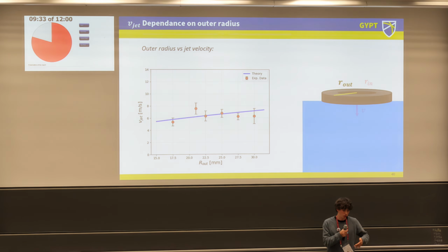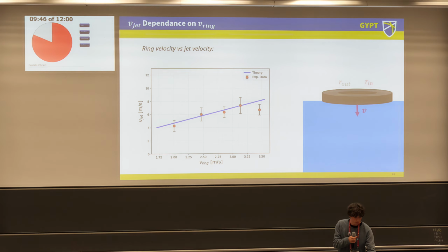Going one step further, and plotting jet velocity over the outer radius, we can see a different thing happening. Here, the jet velocity increases as a greater pressure column is induced below the jet, pushing more water inwards and giving more kinetic energy to the inner jet.